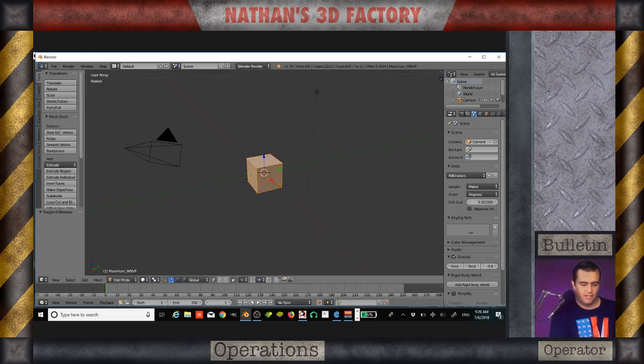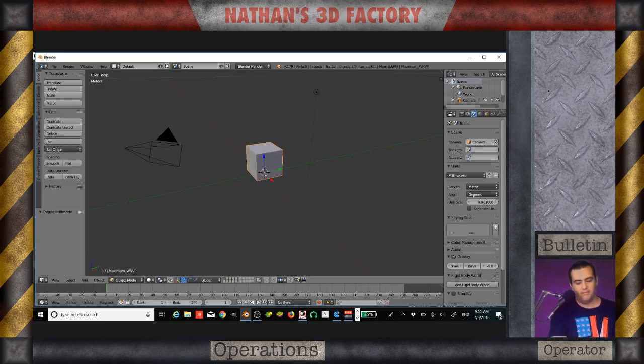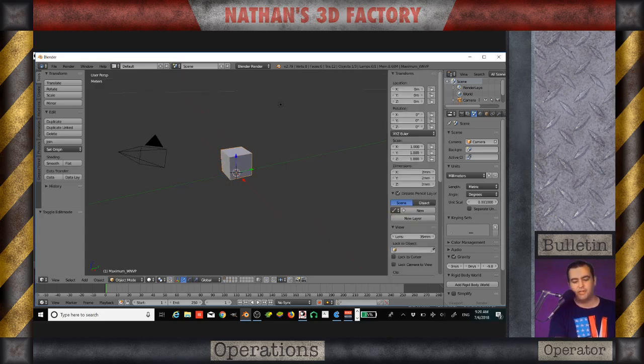So I'm going to tab into edit mode and grab this z-axis up 1. Because right now, our dimensions on this cube, if I press N, are 2 millimeters by 2 millimeters by 2 millimeters. I grab it up 1, it takes it from the center of the cube and puts it as the floor instead. So that's where our origin is going to be. It's going to be very important as we do this.